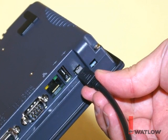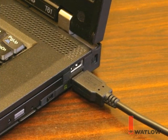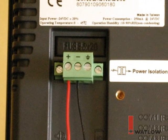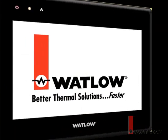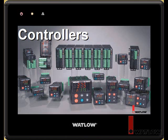Now let's connect the OIT to the computer with the USB cable and connect power to the OIT. When you power up the OIT, it automatically launches the last application that was loaded into it. A new OIT from Watlow runs the default application that displays Watlow products.